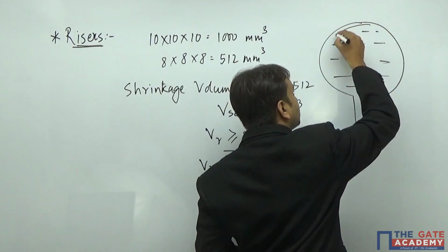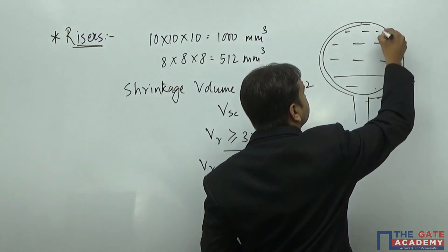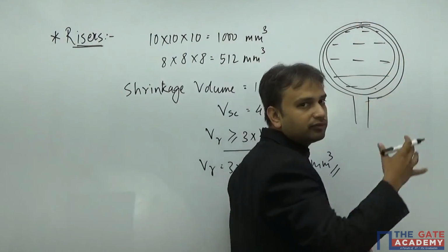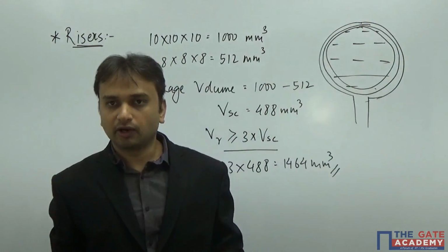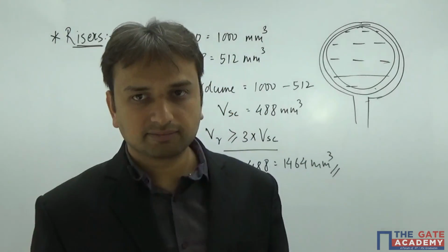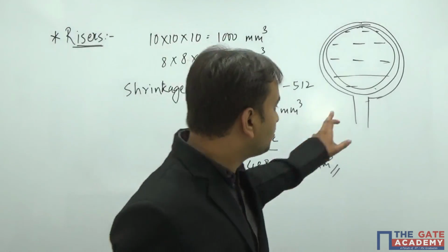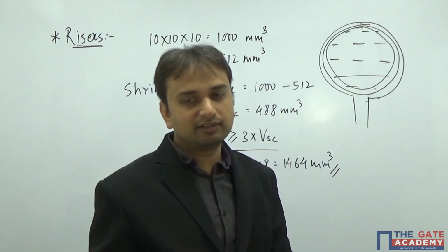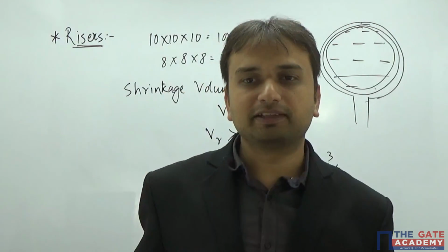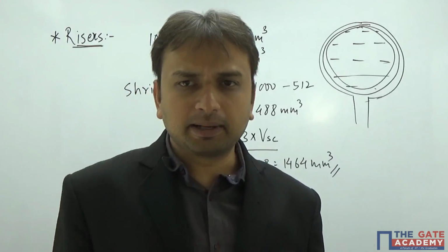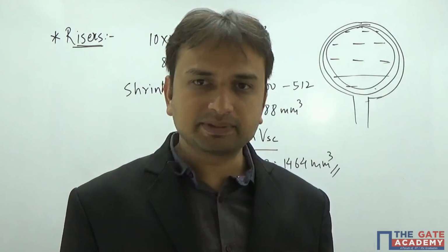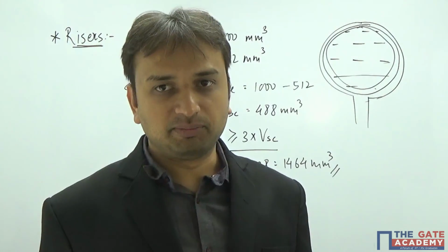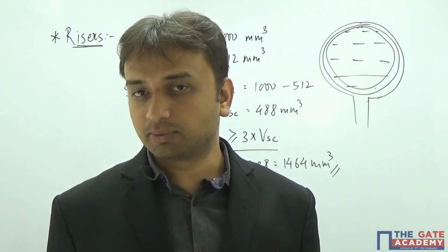This periphery is going to solidify first. Now I hope that you have got the challenge, right? Because it is going to block the exit. It is going to block the path from where a riser was supposed to supply the molten metal. Isn't it? The complete point is gone. The purpose is gone. So now what to do? Then we might have to change the geometry, isn't it?